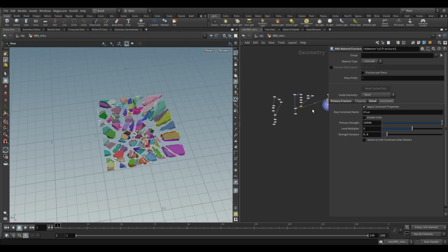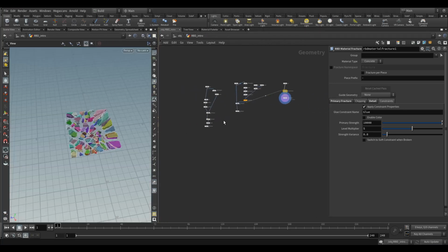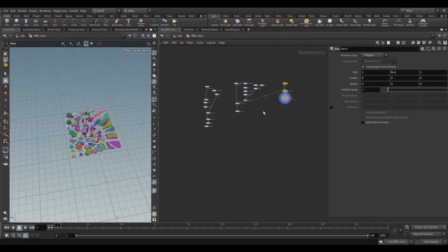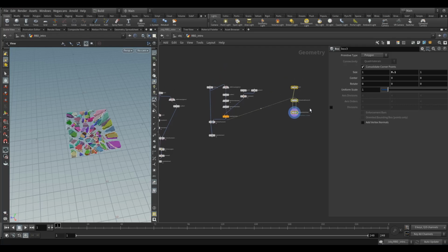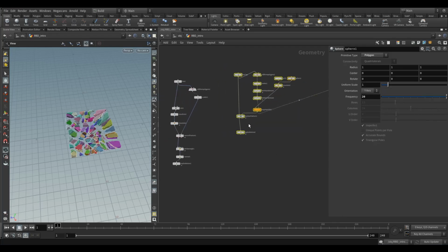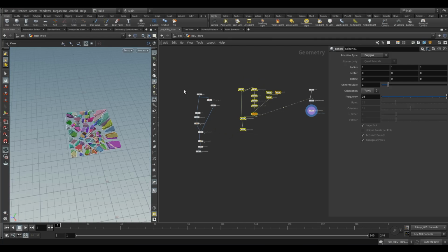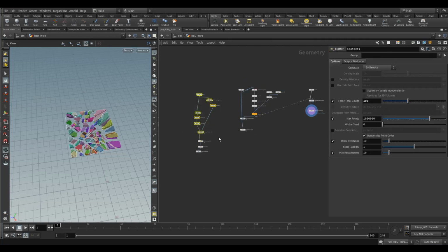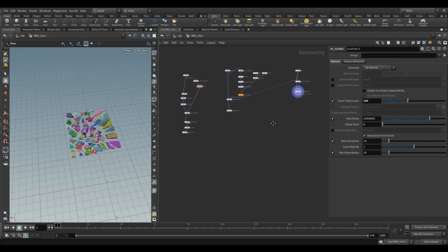Normally for a complex simulation, I'd be using all three. I'd use this for glass and wood. It's a nice pre-built thing. I'd like to use Booleans myself for doing concrete and rocks and things, and then Voronoi for simple things. So when I'm doing bending metal, we need fracture geometry, but very simple, clean fractures. So I use Voronoi for that. So yeah, there you go.